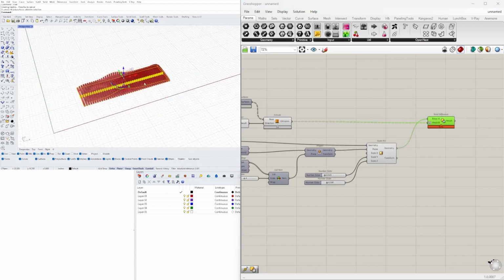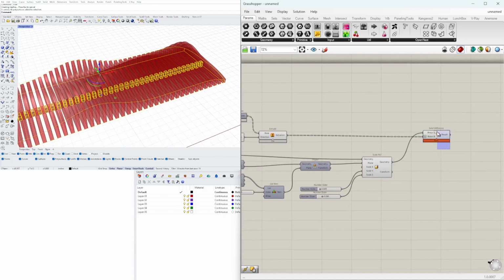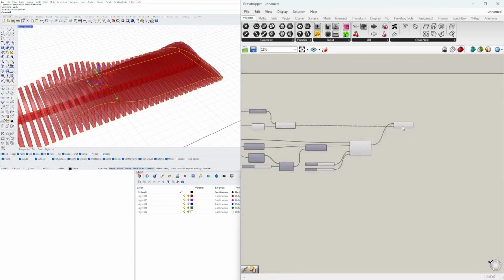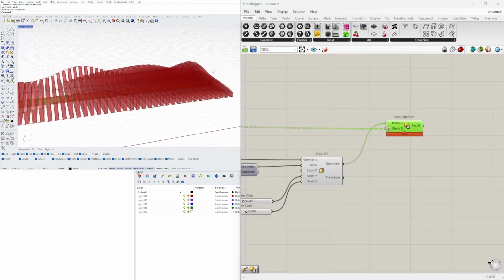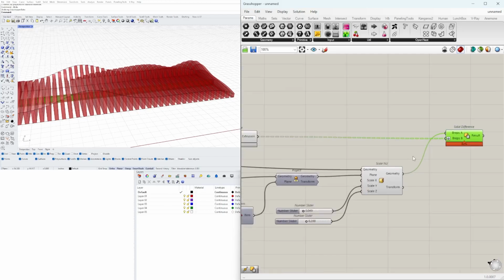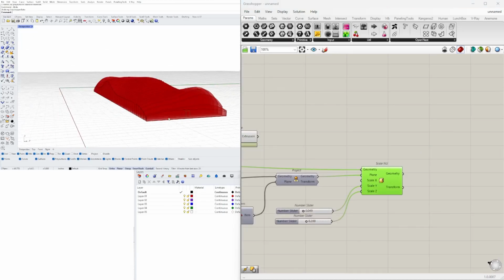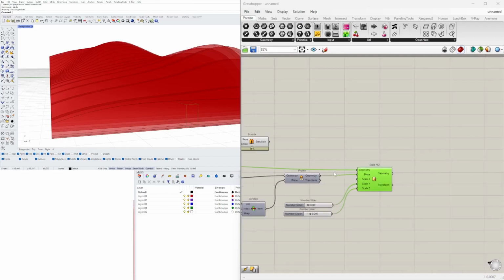So it's going to be a bunch of little blocks. Now I want them to be together, so this is what we have to do. Let's undo this. And rather than creating the Boolean difference right away, we actually have to bring this up by half of the distance. So if this is 0.2, we want to bring it up halfway so it interlocks, and you'll see that.